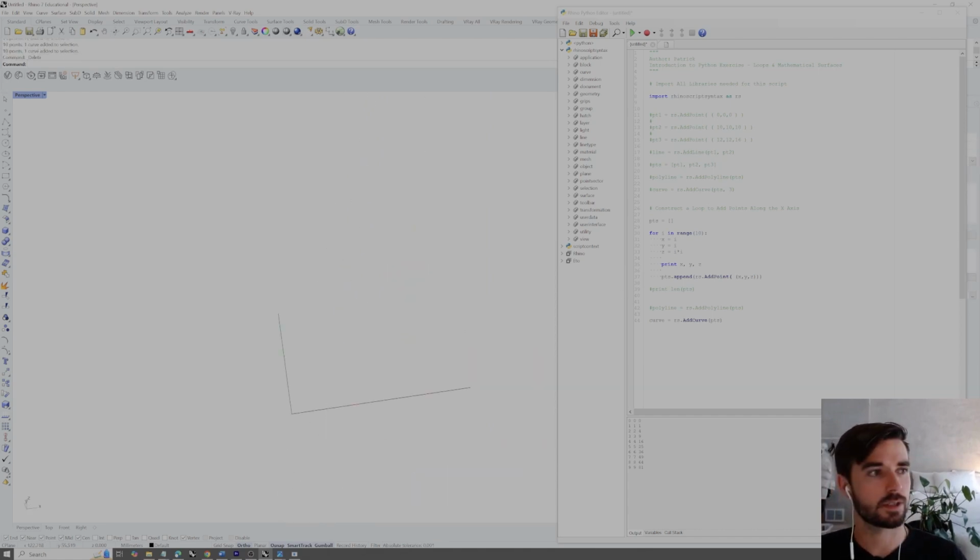Now, this is the basic structure that we're going to need for developing these mathematical surfaces. Already, we're performing mathematical operations to define, or to basically draw out, functions inside of Rhino by setting these equal to increments, whether that's linear, so 0, 1, 2, 3 to 9 for both the x and the y, or in the z using exponential. We could also just add a factor here to increase the slope in this one axis. So instead of y equals i, we could say y equals 2i, or 2 times i.